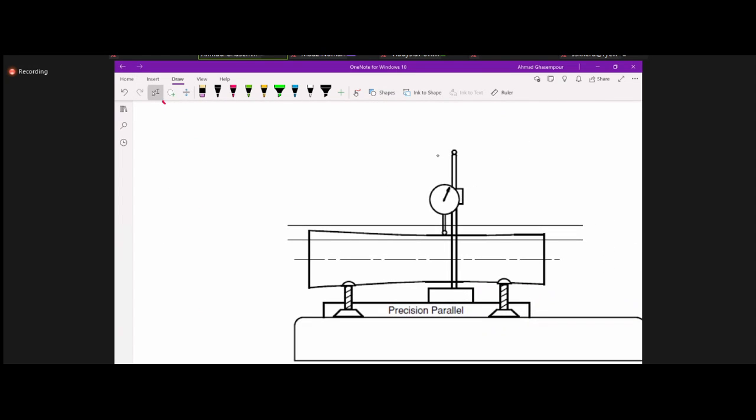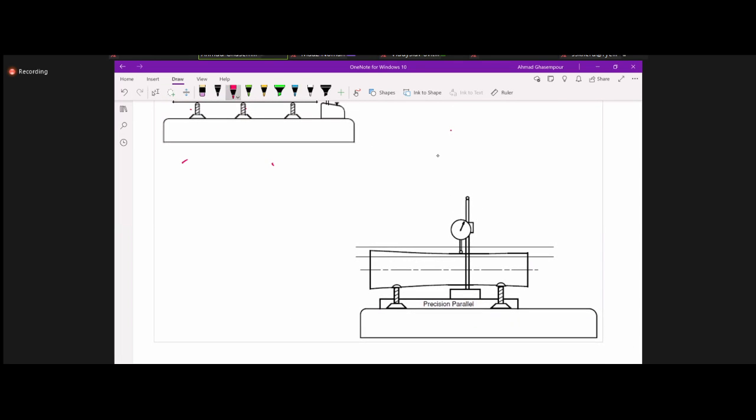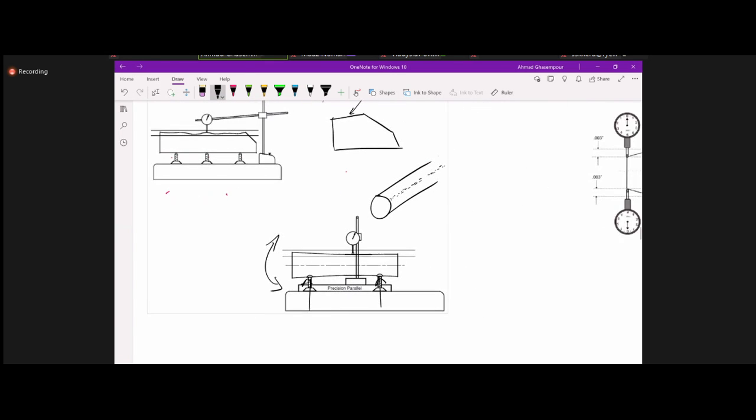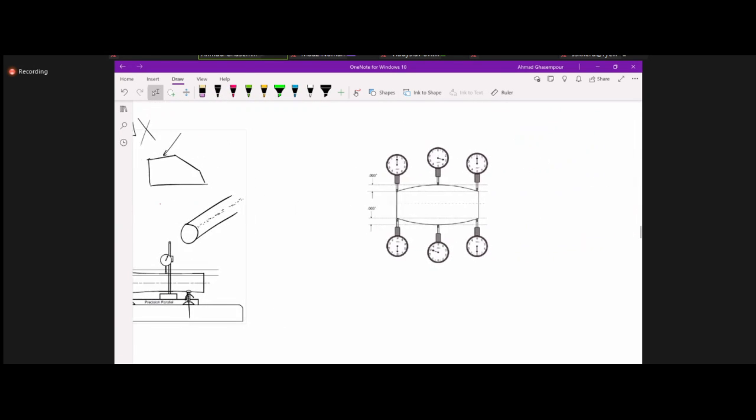Again, you see it here. So this is a cylindrical part. If I want to try to inspect this line on it, I have to inspect just the line on the top surface. But because I have to set it up in some sort of arrangement, these become datums if I'm not careful. So again, you have to kind of tilt it until it's optimum flat or level, and then do the measuring. There are some tricks that you can do.